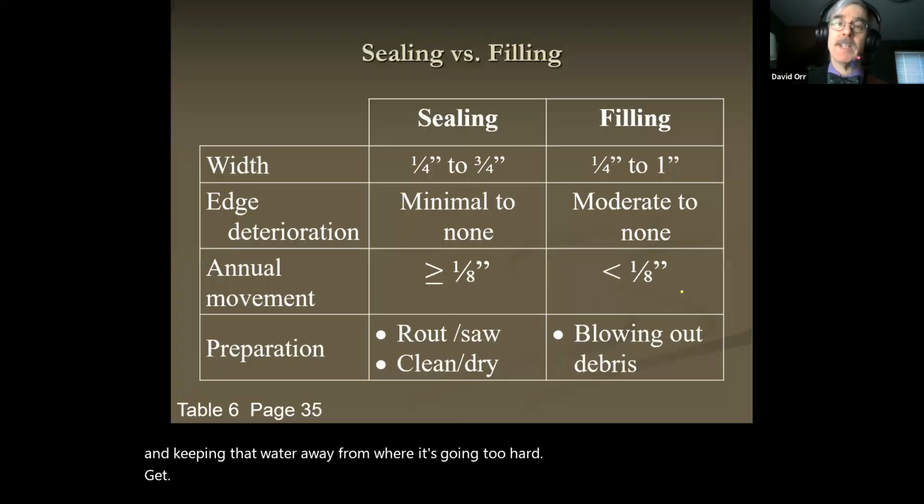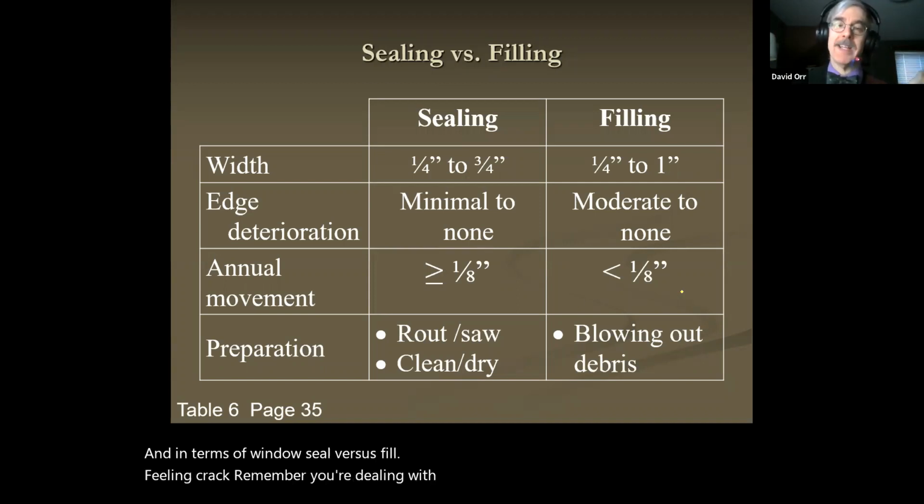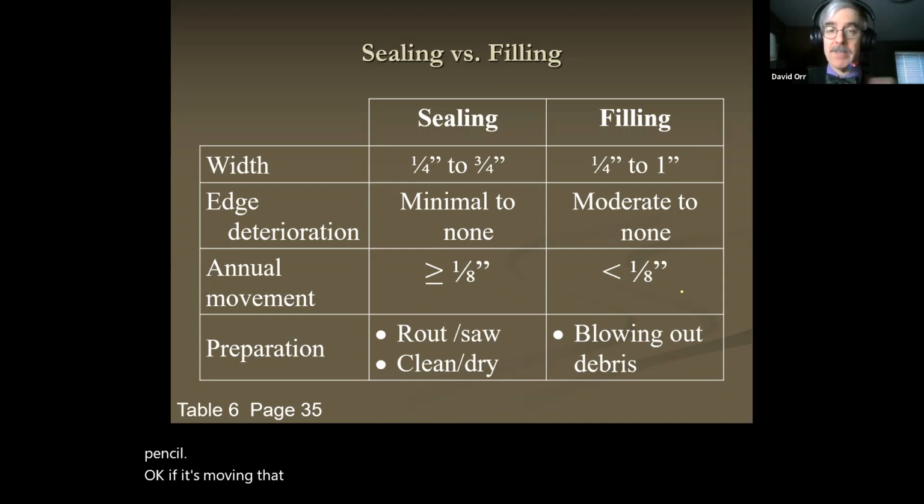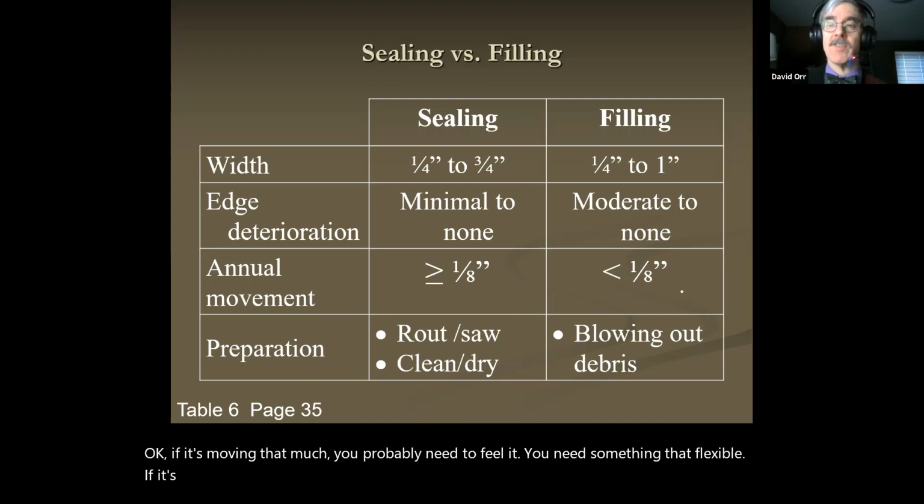And in terms of when to seal versus fill, for a sealing crack, remember, you're dealing with movement. So the annual movement is 1/8 inch or more. That's about the thickness of the pen that I've got here I'm writing on the screen with, or a pencil. Okay? If it's moving that much, you probably need to seal it. You need something that's flexible. If it's not moving, you can just fill it.